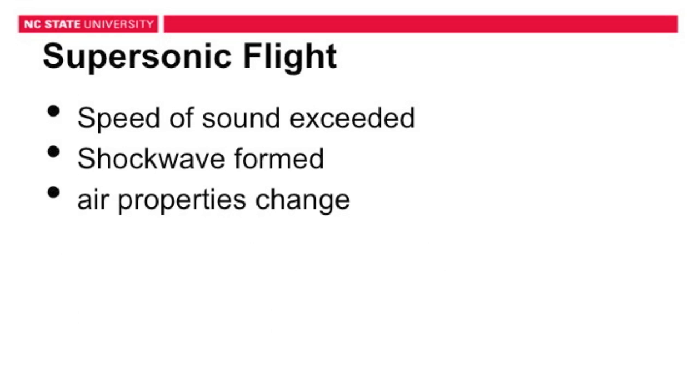In supersonic flight, the speed of sound is exceeded and a shock wave forms over the body. Across the shock wave, the atmospheric conditions, pressure, temperature, and Mach number change. For example, the Mach number after the shock wave is lower than the atmospheric Mach, whereas the stagnation pressure increases across the shock.